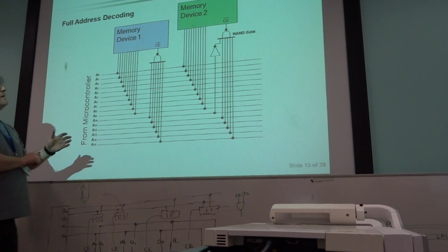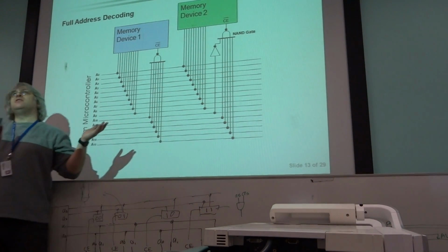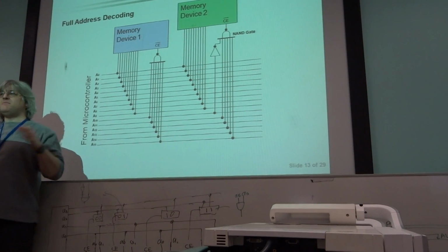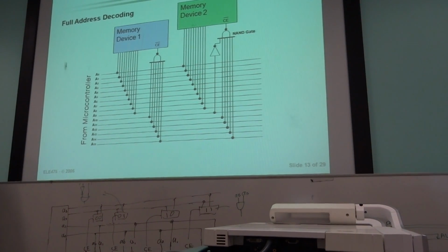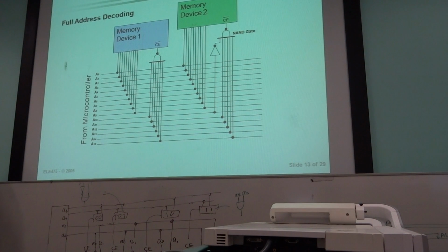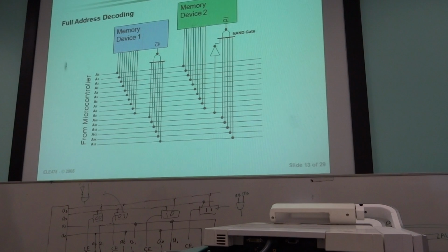It's true. The other one, the problem is, one way or another, one of those two RAMs is always going to be on. Okay? Now, if those RAMs are connected to your data bus, that data bus is always in use. It's either in use connected to RAM 1 or it's in use connected to RAM 2. So you can't use your data bus for anything else. Because if you try and connect it up to something else as well, you've got a conflict. But the RAM is still on.